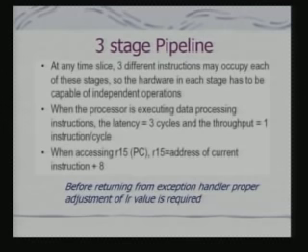This is different in the case of exceptions like data abort or prefetch abort, where the exception occurs during execution of the instruction. But in the case of FIQ or IRQ, the interrupt is serviced only on completion of the current instruction. And in this case, PC points to PC plus 8, and this value gets loaded onto LR.